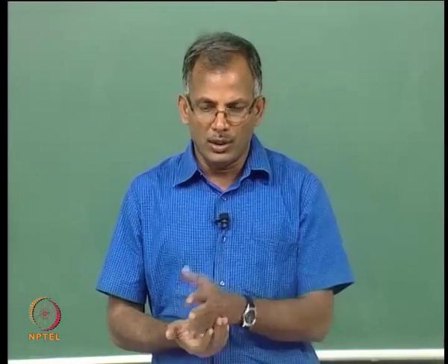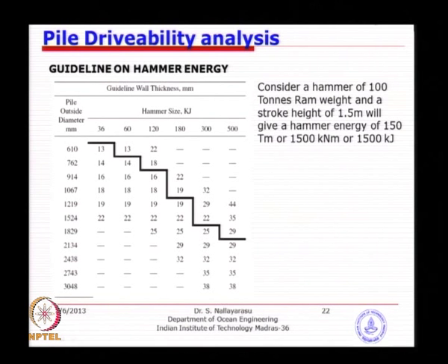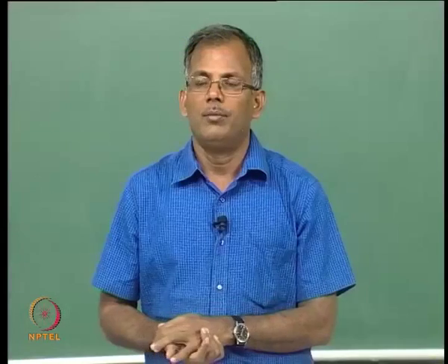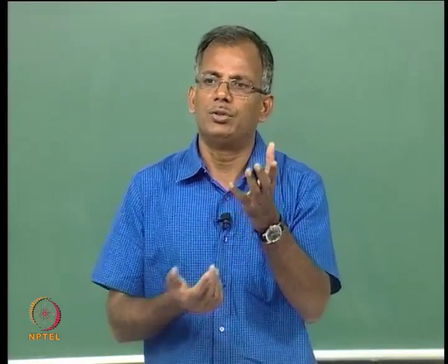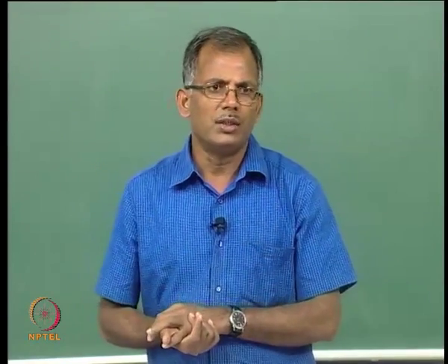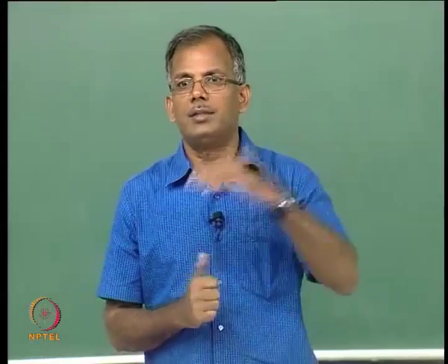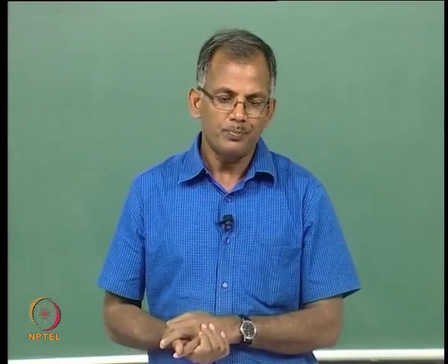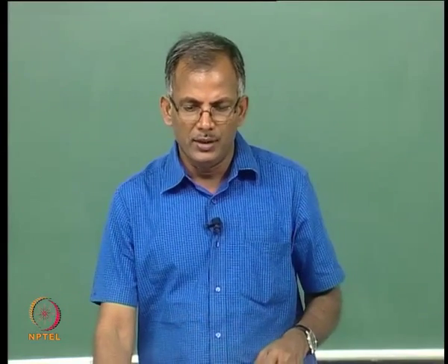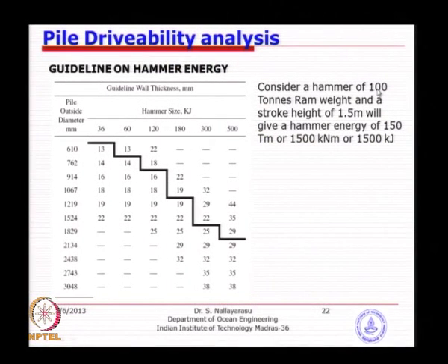For example, if the ram weight is 100 tons, the whole weight of the hammer is 200 tons. When you place 200 tons, maybe it is not a very big stress because your pile is designed for 1000 tons, but it will be very large because it is a cantilever. After final installation, maybe it can take 1000 tons. That is where you have to look, and because of the dynamic impact of the 100 tons, the dynamic stress also will be quite large. We will be looking at that.